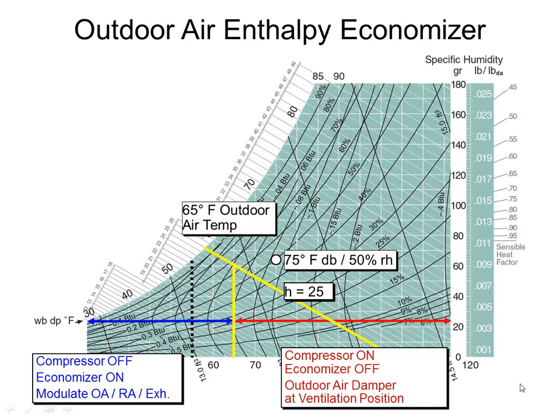If I do the enthalpy, then I get this angled yellow line, right? I'm looking at temperature and moisture content to decide which air is better. So in this example, anything below 65 and dry, then I can kind of deal with that. And that basically gives me this extra area I'm circling here in red. Those are extra run hours that I didn't have when I have a straight line at 55, right? I can't claim those extra hours. Enthalpy-wise, I'm pretty good down here, but it's just going to be too warm for me to work with that air. So economizer over here that I otherwise wouldn't have had, and then mechanical compression on this side over here.